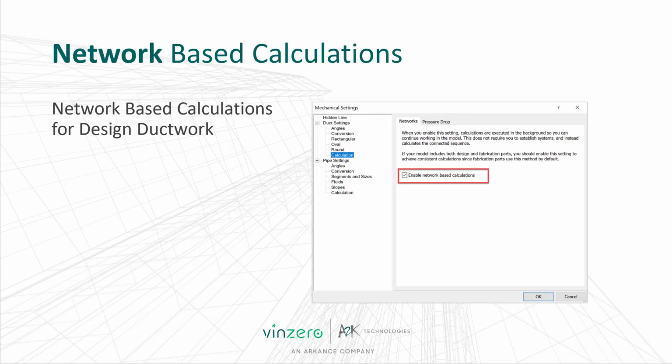Network-based calculations for design ductwork. Accessing this feature within the Mechanical Settings or Ductwork tab allows ductwork design calculations to run in the background while you continue to work. On large-scale models, toggling this feature off or on can increase your productivity.